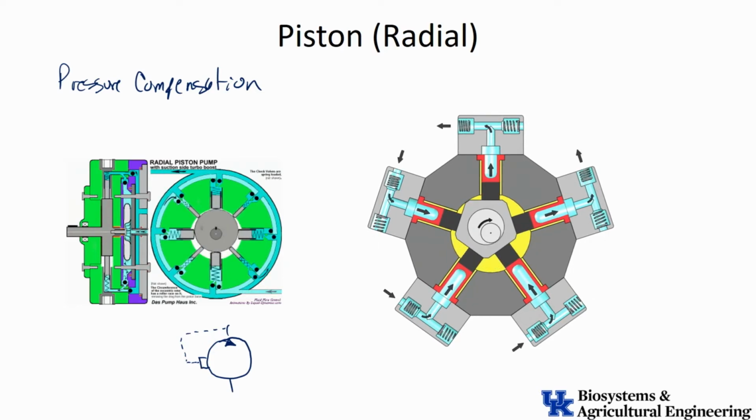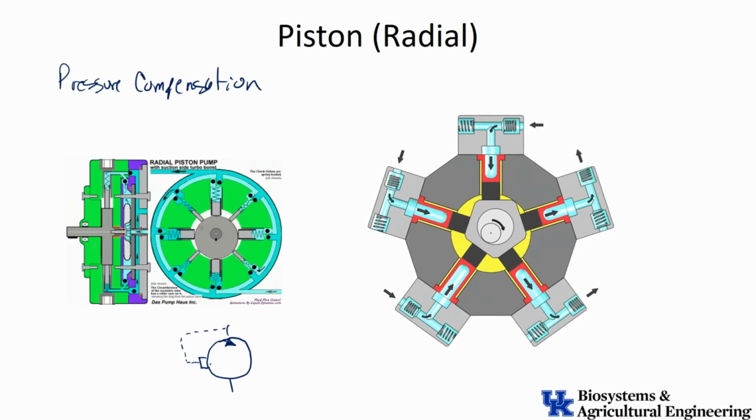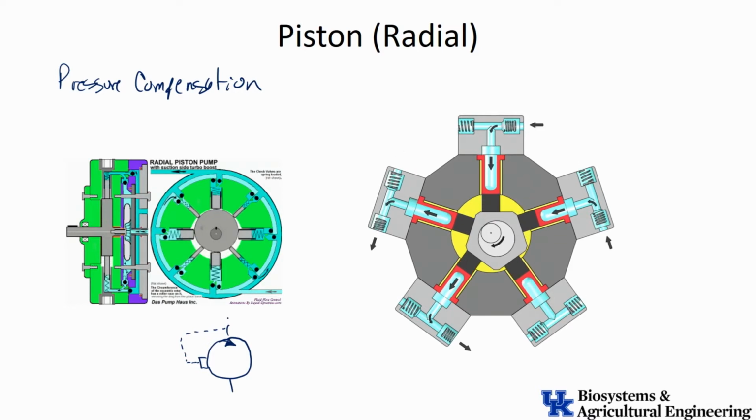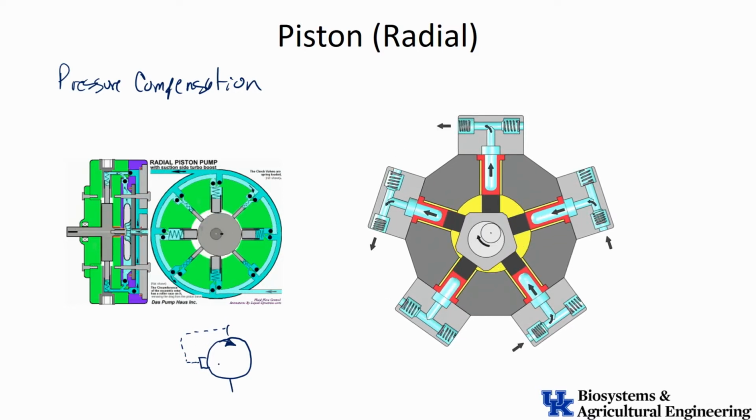And so we can kind of see graphically here that we're telling the pump down here to do something, and that will, in this particular case, like the radial piston pump, tell it to de-stroke and say, hey, we're going to break something, so quit sending oil down there. Don't keep pumping it because it's got no place to go.